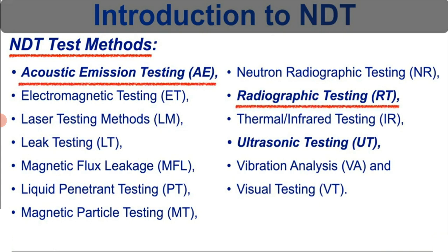Next objective of NDT is determining the position and condition of reinforcement. So what types of defects? Cracking, spalling, staining, construction and design defects, honeycombing, dusting and blistering.